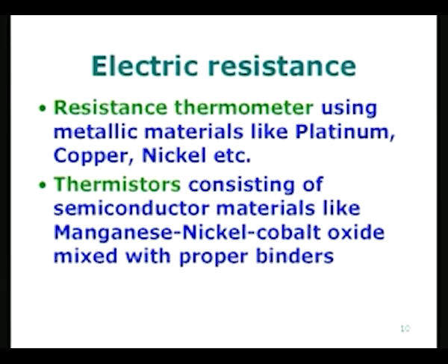Actually, the resistance increases with temperature, and this increase with temperature is characterized by a regular relationship, and that relationship becomes itself the basic interpolating formula for the platinum resistance thermometer.